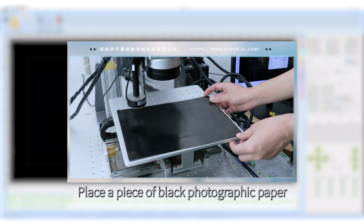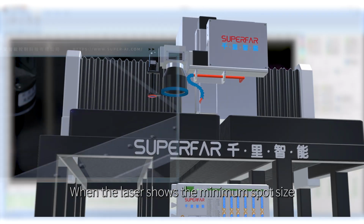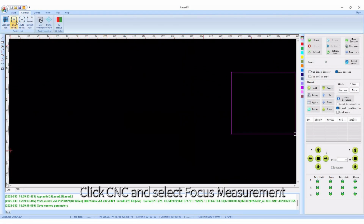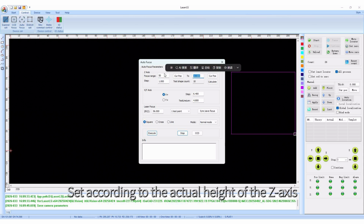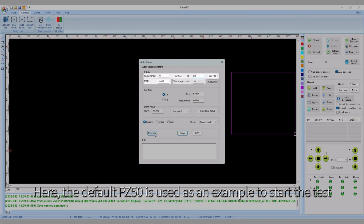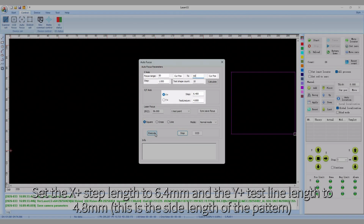Place a piece of black photographic paper, turn on the laser and move the focal length up and down. When the laser shows the minimum spot size, record the PZ value. Click CNC and select Focus Measurement, set according to the actual height of the Z-axis. Here, the default PZ50 is used as an example to start the test. The step length is 1 mm and the automatically calculated number of tests is 10. Set the X plus step length to 6.4 mm and the Y plus test line length to 4.8 mm.